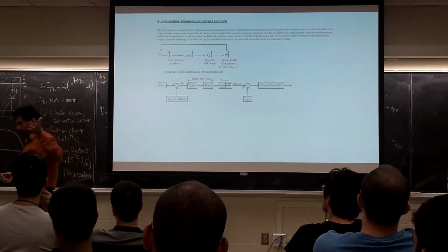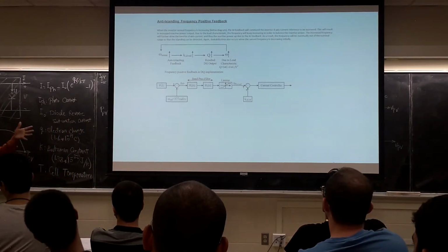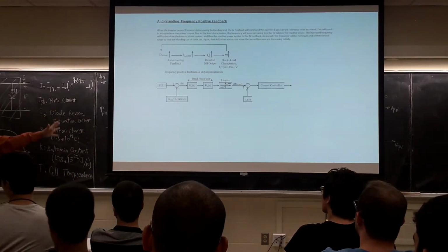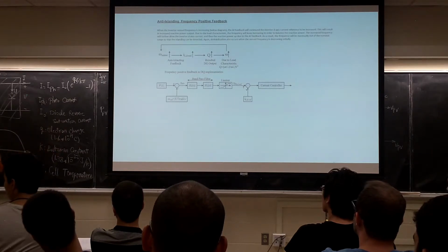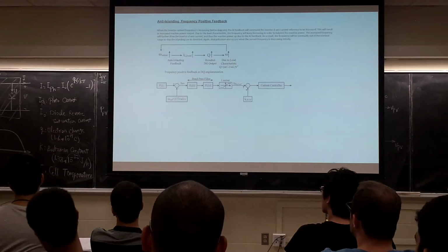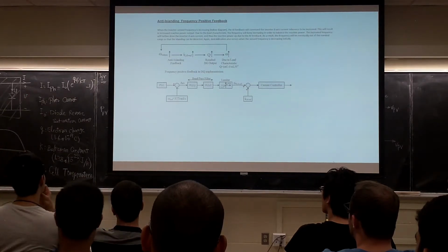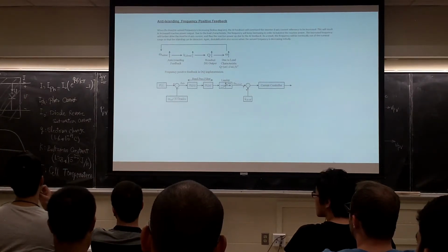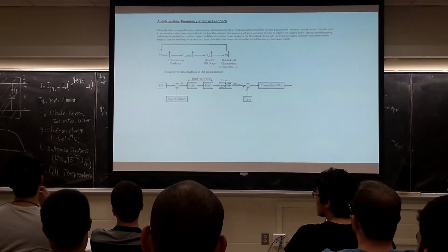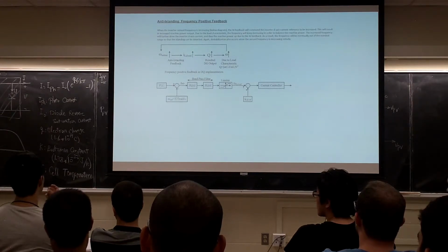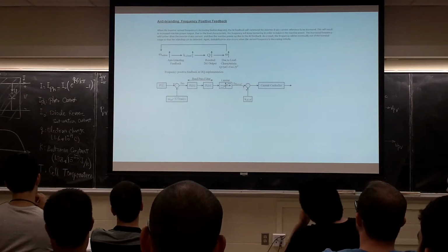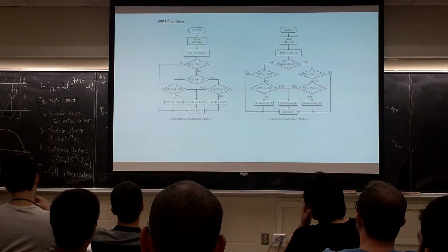Most probably the project, I don't know very much about it, needs somebody to verify all these things for this inverter, to make sure it does the reactive power support, the active power support, voltage support, and anti-islanding. These are the kind of things a smart inverter does. It's not the design of the inverter and its control, but test and verification of this, and it still should be a fun project to work on. But now let's go back to what we were talking about. Two algorithms.